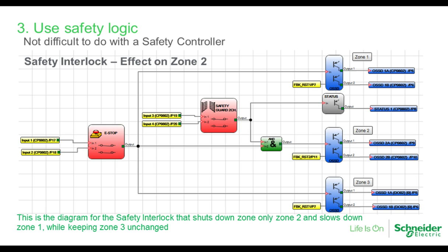There's a good chance you don't even change your wiring at all. All your sensors are still connected to the same place. Your motor controls or robotics controls, whatever you're doing, are all on the same outputs. You've changed your logic. And now you have a way, even on your HMI or your SCADA systems, whatever your operator is interfacing with, to even know, hey, this door is open, so I'm in the door is open mode, which means I'm doing this and that, right?